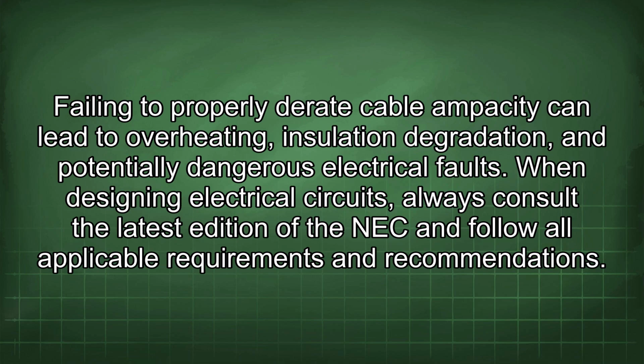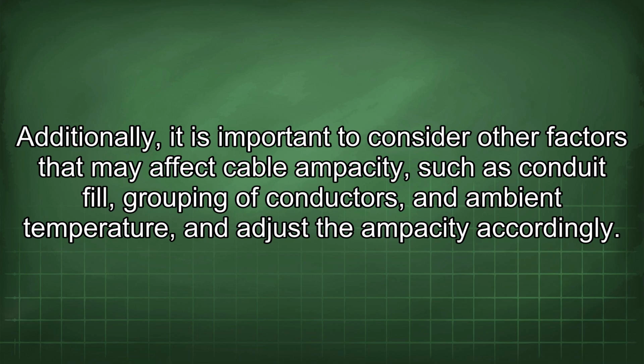Failing to properly derate cable ampacity can lead to overheating, insulation degradation, and potentially dangerous electrical faults. When designing electrical circuits, always consult the latest edition of the NEC and follow all applicable requirements and recommendations. Additionally, it is important to consider other factors that may affect cable ampacity, such as conduit fill, grouping of conductors, and ambient temperature, and adjust the ampacity accordingly.